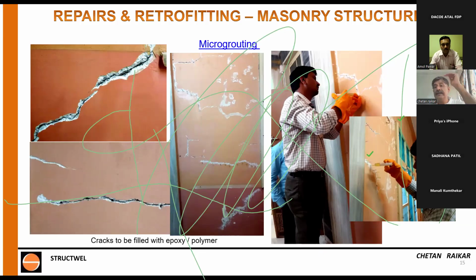If you replaster, these cracks will reappear, because in replaster you will still have air in it. So you need a material that is strong, which resists the expansion and contraction of the air. That can be achieved by this micro grouting. We have successfully tried this a few years back. We are using it for almost 12 to 15 years now, very successfully.